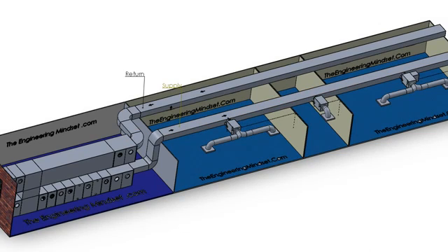And that's really handy because not every room in the building will experience the same heat load. But with a VAV system, you'll be able to control the amount of cooling, or possibly heating, into each of the rooms individually from the same main ductwork and main AHU system.